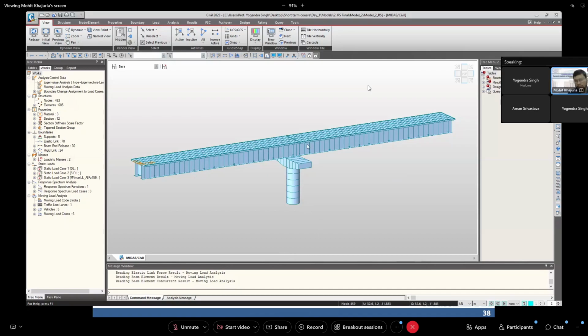In the Y direction, which is the transverse direction, the shear which we have to check is also in the Y direction. Local and global Y directions are in the same direction, so we have to check just FY. But for the X direction, that is the longitudinal direction, the shear is also in this X direction. This X direction is locally the Z direction.